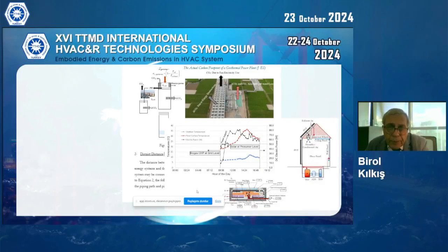It uses heat pipes. And another example that we should be careful about, let's say this is a geothermal well where you just cool the system by electrically operated fans. And these fans, of course, lose the opportunity of using the heat in a district heating system, just rejecting it to the air.